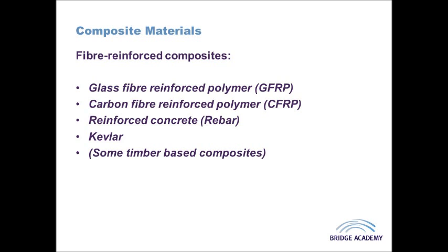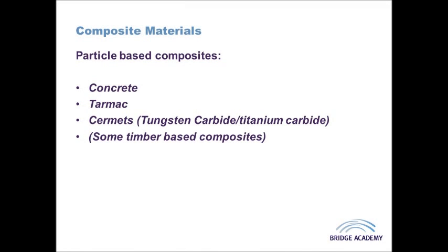Now, the third key area of composite materials is particle-based composites. Now, particles, as you would imagine, are very small materials or parts of materials that are kind of bonded together. Now, the advantages of particle-based composites, or their properties effectively, is that they have very high strength under compression, as I discussed with concretes, though not so much in tension, hence why in concrete it's often important to reinforce the concrete. They've got a uniform structure, as we talked about with things like MDF, and they're normally free of surface defects.